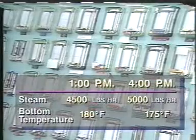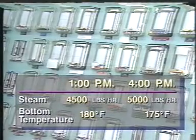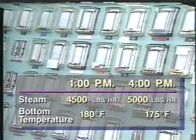of tower conditions. Suppose instrument readings tell you that the flow of steam to the reboiler has increased and that the temperature at the bottom of the column has decreased. Other tower variables remain the same. Does this data fit together? If you answered no, you are correct.